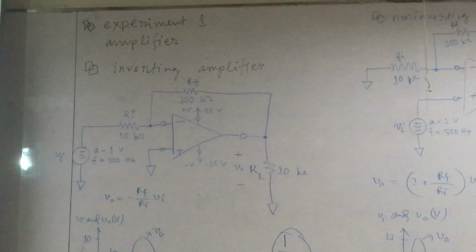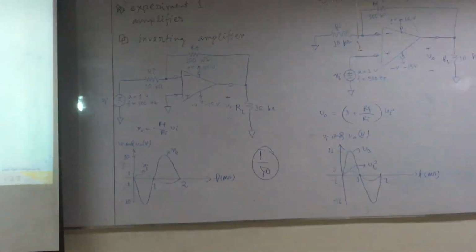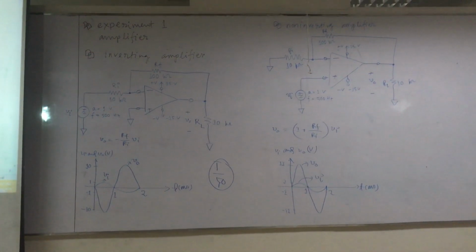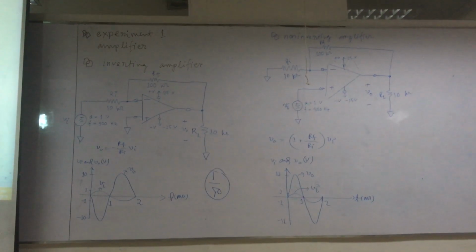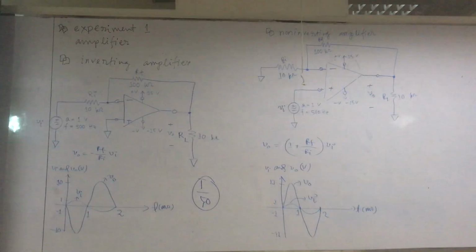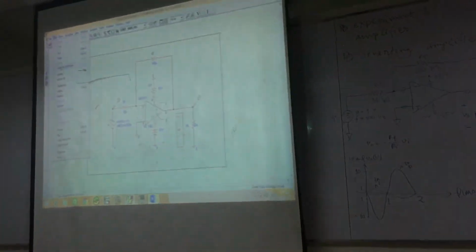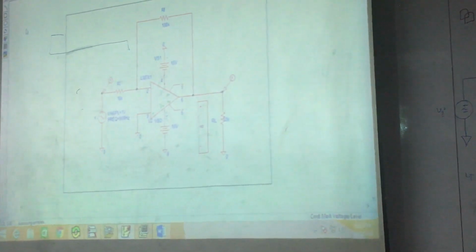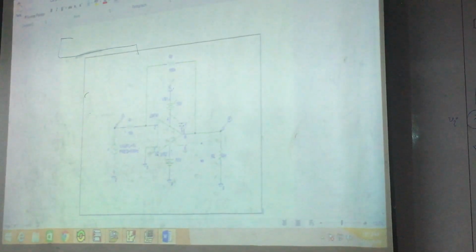You see? Now you need to, I forgot. There are plenty of dots here. Before clicking copy to clipboard, remove those dots. How? Options, display options, grid on. Check that option off. Then the dots are going to disappear. Then click on copy to clipboard. Then paste it. So this one, delete it.